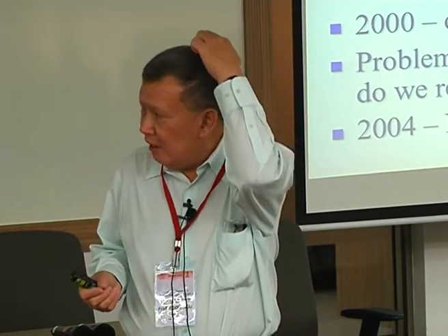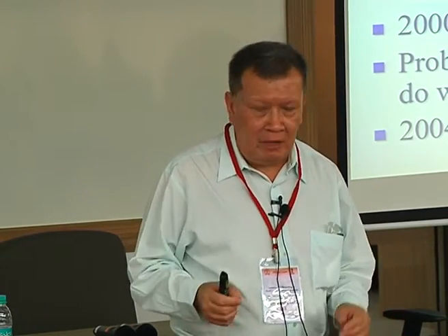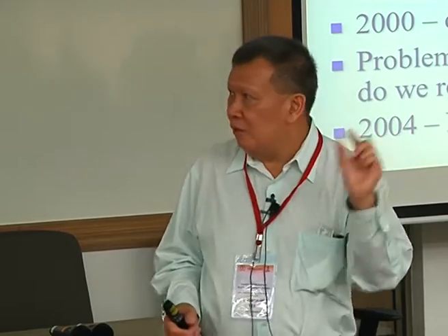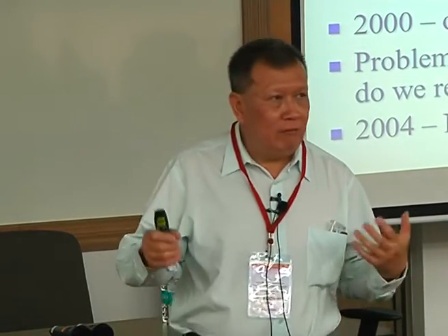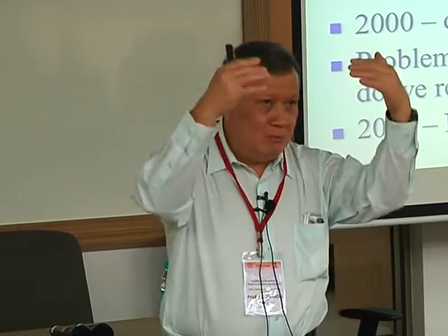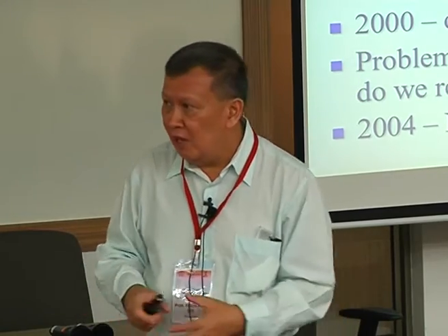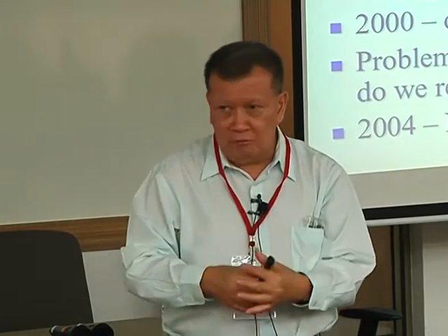The second thing is that, in the very, very early stages, people were using charts like Terzaghi and Peck and things like that. But it was found very quickly that those charts are not sharp enough to provide the kind of numbers you need, which is about that much movement. So basically, they started looking for other things. And ground movement doesn't just mean lateral movement, but it also means surface settlement, ground settlement. There are also rules governing how much the ground is allowed to settle.